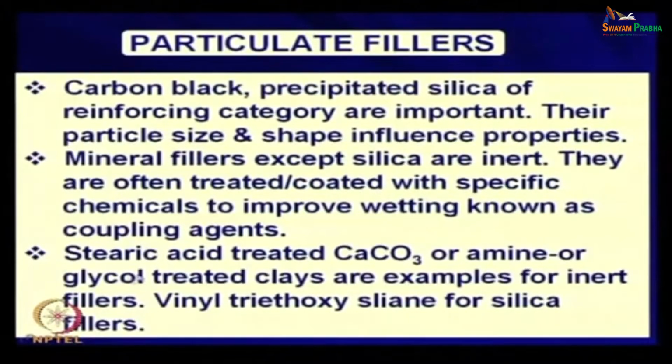Now, that can be improved if you give a very thin coating to the filler particle. Here is an example of stearic acid treated calcium carbonate. Calcium carbonate is an inert filler, but you can disperse it more easily in a hydrocarbon or an organic polymer if you make a thin coating of organic material.